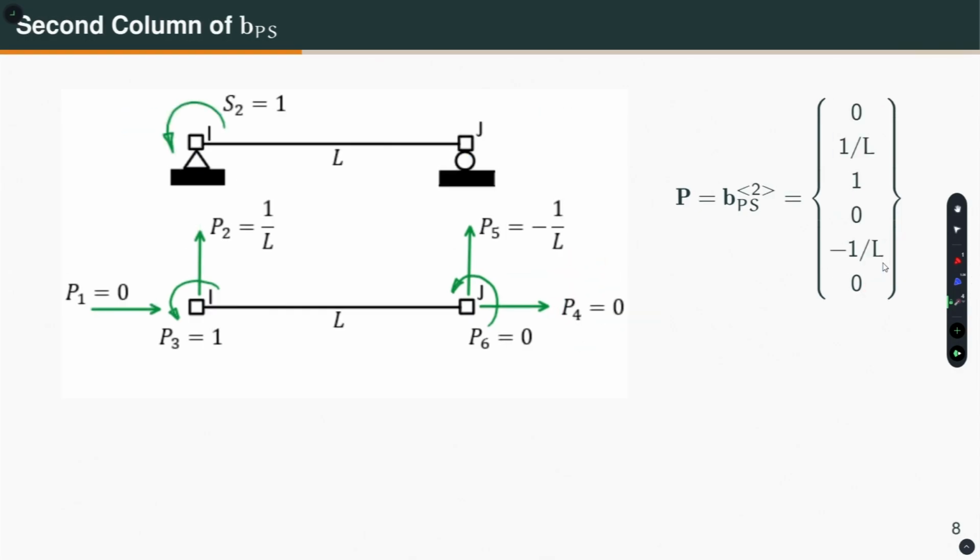Similarly, if I apply S2 equal to 1, that means now I am applying a moment, right. I am applying a moment, S2 is equal to 1. How do I determine the forces? Well, using simple statics, what I will do? You are applying a moment like that. So, this will be the reaction. What is the reaction? 1 by L, and this is also 1 by L, right.